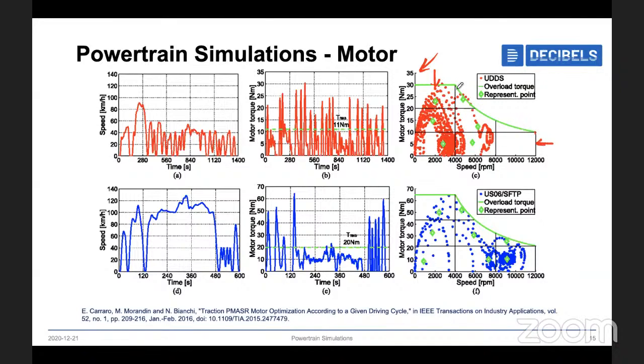If you plot these operating points, we'll get to understand where your motor is operating. From this image we can understand the motor is almost operated in the max torque region and at higher speeds. Similarly, this is for a particularly different application, but for your case you can plot like this and understand where exactly you're operating the motor. And you can also plot the efficiency map along with this.